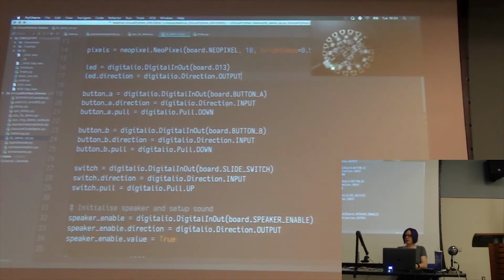And because the fruit has a capacitive touch to it, that's when we added touch threshold, actually. So that's the other cool thing about this, is as people run into problems, they come to the community and say, hey, I'm having this issue, it's not working, and we say, okay, either it's a bug or maybe it's something you're doing, but we sort it out, and when it's a bug, we fix it. When I initially did that project, the threshold was entirely too small. All of them were setting each other off. I could hover my hand over the top of them by 2 inches and set off a touch event. So it was like a theremin. You made a theremin, right? So we added touch threshold to the library specifically to fix this issue.